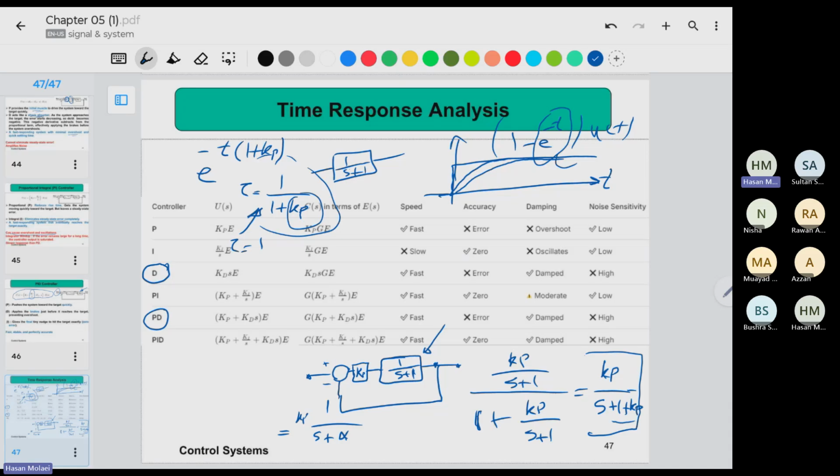So the single pole is simple. You can do all of these things by hand calculations. For the second order, it is still doable. For higher order it becomes more complex. Because for the single pole, you are not seeing any stability issue because it still remains a single pole. Just to give some intuition to you: when we say that the proportional is helping to increase the speed, how? With a single pole example for yourself, you can get a sense of how it is changing. It's basically manipulating the time constant.